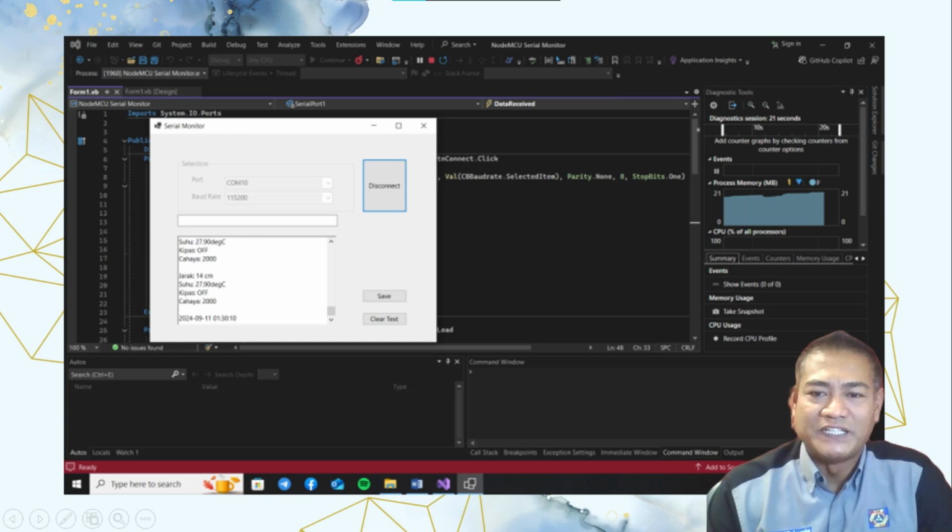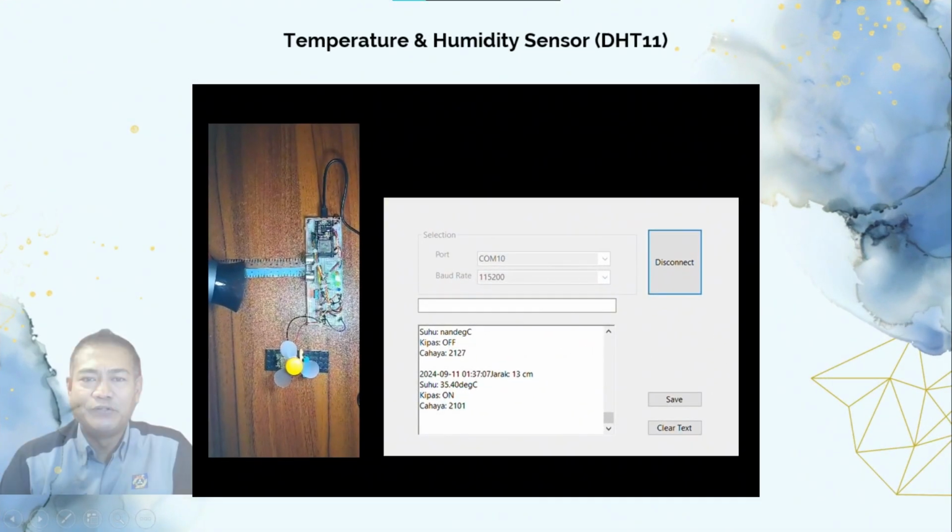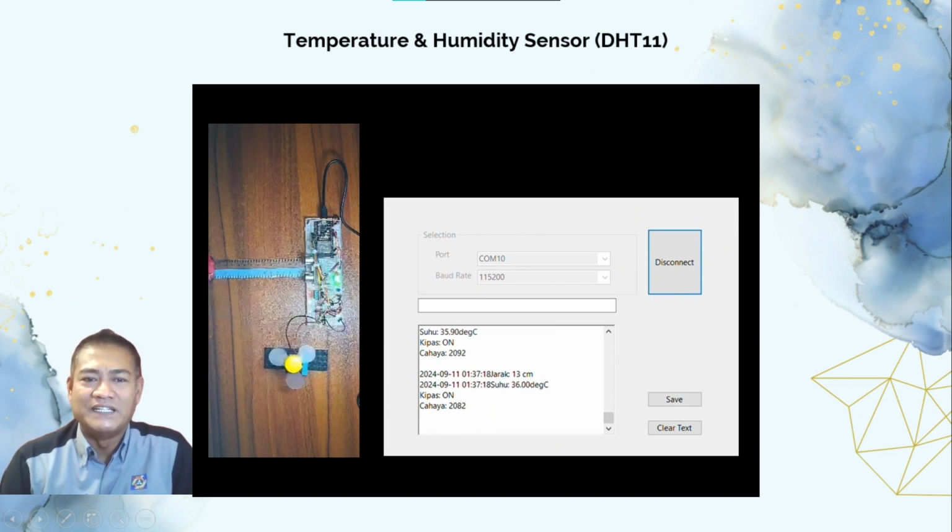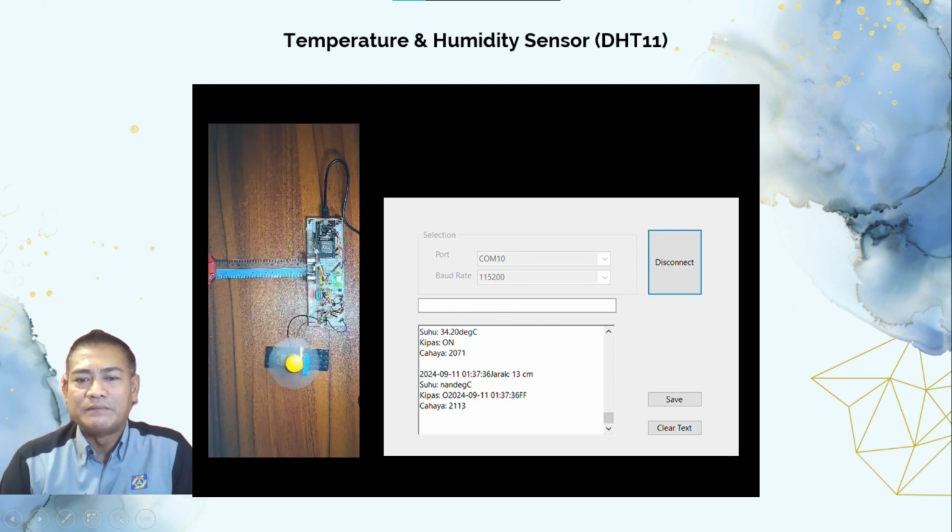the system's functionality efficiently. In this video, you'll see how we program the Arduino system to control a fan based on temperature readings. Specifically, the system is designed to activate the fan when the temperature reaches 30 degrees Celsius. Once the sensor detects that the environment hits this threshold, the fan automatically switches on. If the temperature drops below 30 degrees, the fan will stop running, ensuring energy efficiency and maintaining optimal temperature control. This setup showcases how automation can simplify everyday tasks, providing a responsive system that adjusts to environmental conditions in real